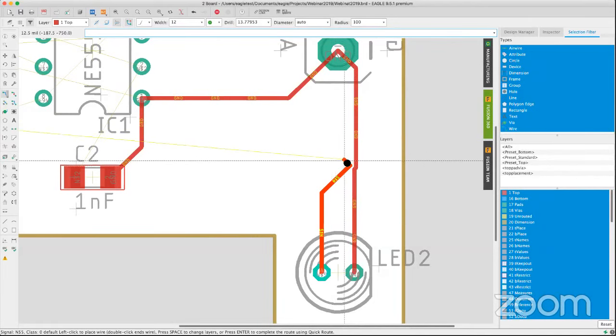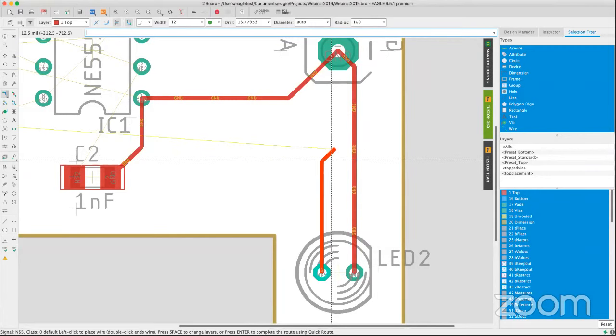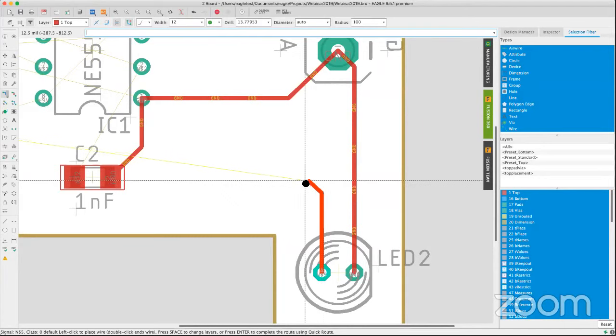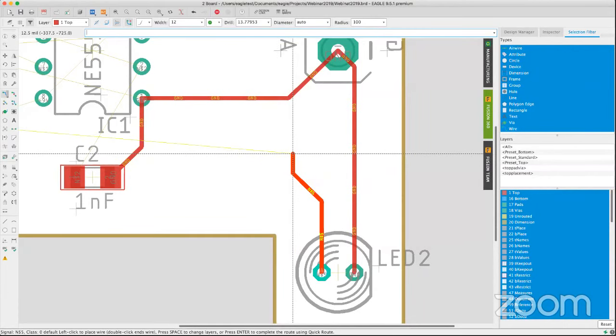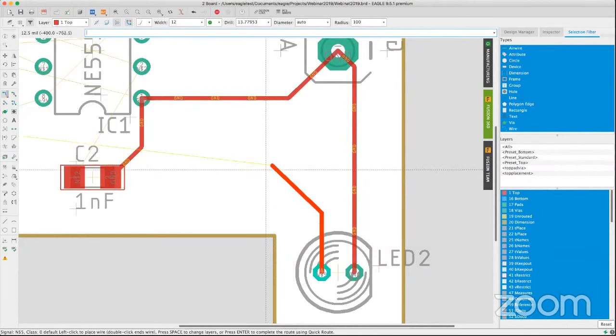Now, if I'm routing and I did a left click and I have a point of bend there, and I want to go back, you only have to hit the backspace and it will return. It will eliminate the bend. And if you have many bends, let's say I go 1, 2, and 3, I can now hit backspace, backspace, backspace. That way I could backtrack.